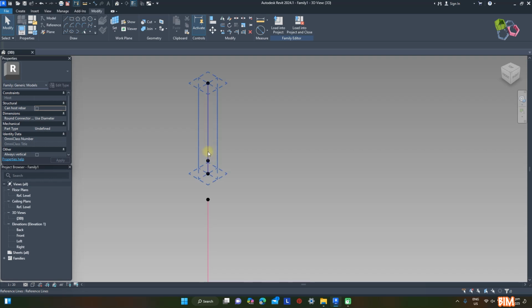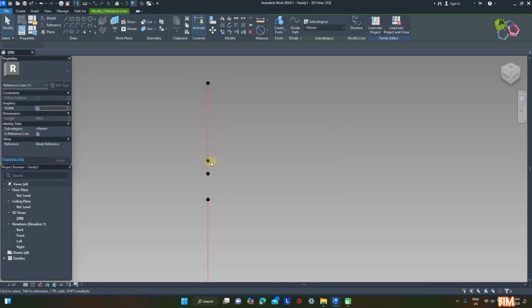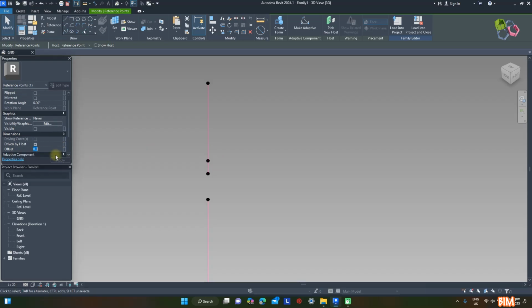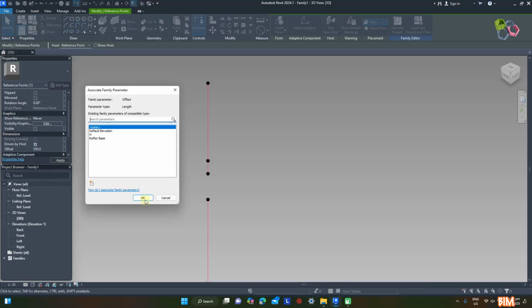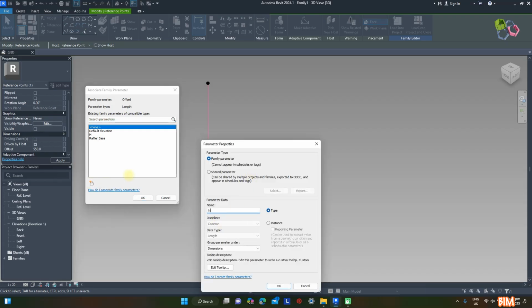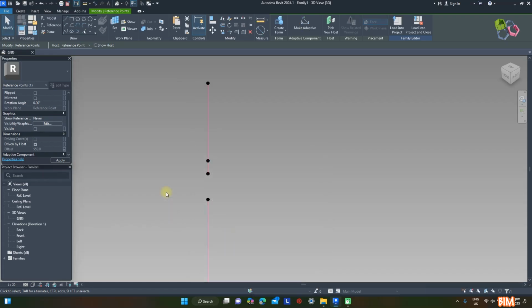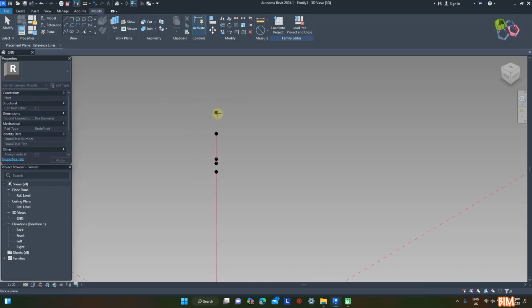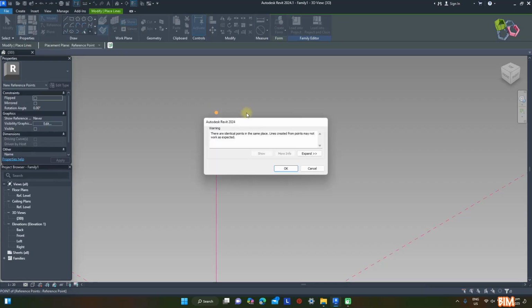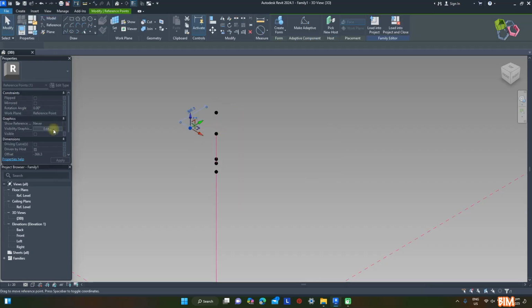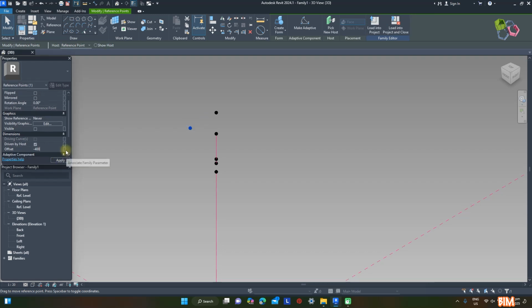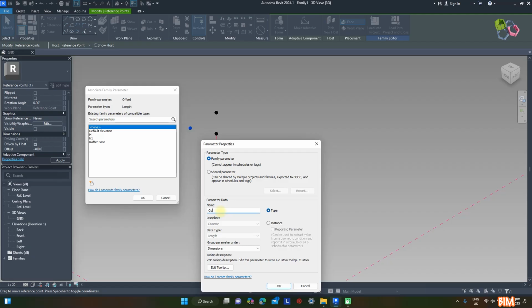Next, create a point for the roof frame. To do that, reference it with a parameter h1, and ensure it is placed on the horizontal plane. Set at 550 mm offset, this point should be above. Referencing this point, using a vertical working plane, place a point to define the roof back offset, dragging some distance back in a different movement direction, and give negative 400 mm. This should be controlled with a parameter. Define the parameter as covered back.